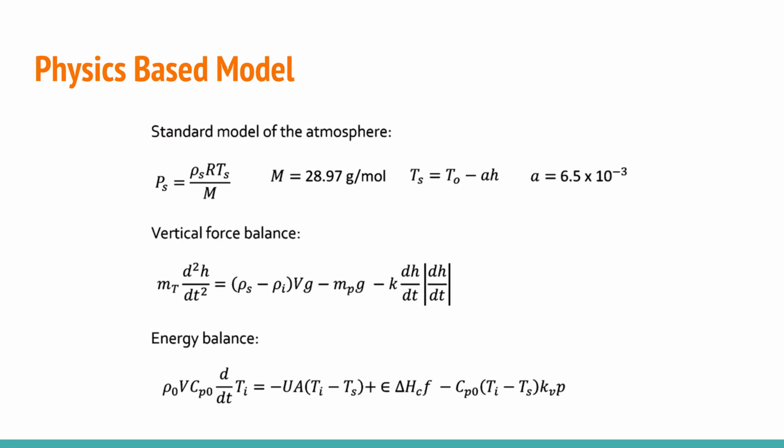So the fundamental basis behind our controller is the physics-based model that was provided to us by Dr. Badgewell. It uses a standard model of the atmosphere, and the balloon runs on two fundamental balances, one being the vertical force balance that takes into account lift, gravity, and the drag force acting on the balloon, as well as an energy balance acting on the hot air balloon gases, where we have convection with the atmosphere, as well as heat addition through the combustion of the fuel gas, as well as hot gases leaving through the vent, which pulls energy out of the balloon.